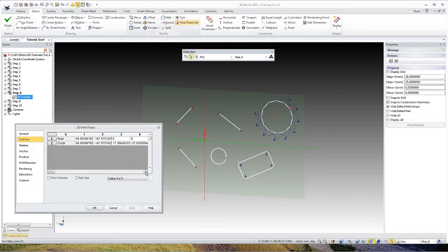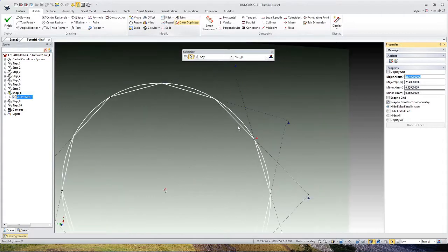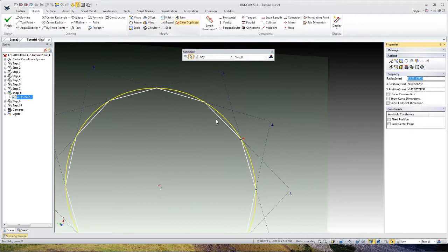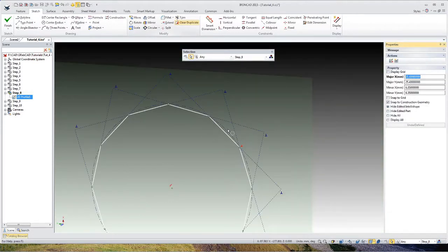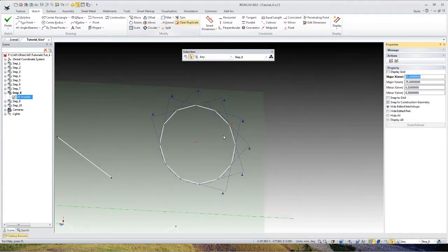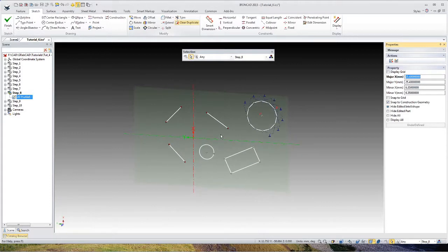What's going on there? Well, if we scroll across and change this last number here to a 1, number 2 is construction geometry, change that to 1, and OK that, you can actually see that the circle was behind this polygon, and it was used as the constructor when we made that polygon. And it was actually hiding there because it was construction, and we couldn't quite see it because of these extra construction lines. So that's a couple of tools for finding problems.